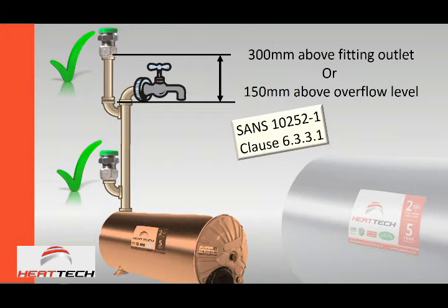If there's water, a practical example, on the second floor, somebody's been doing washing in a top loader washing machine, for instance. There might be a pipe connected from the tap to the top loader washing machine. The tap is open, and something goes wrong. It is quite possible that water gets sucked out of that top loader through the tap down the bottom, except if there's a vacuum breaker fitted in the right position, 300 millimeters above that. Then the water will take the easier route, drain the air through the pipes, and you won't have that.